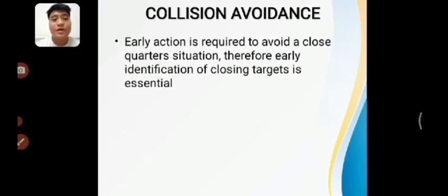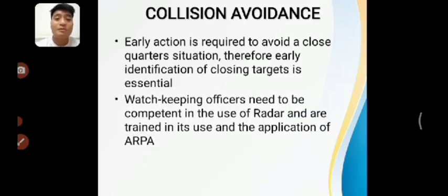Early action is required to avoid close quarter situations. Therefore, early identification of closing targets is essential. Watchkeeping officers need to be competent in the use of radar and trained in its use in the application of ARPA.